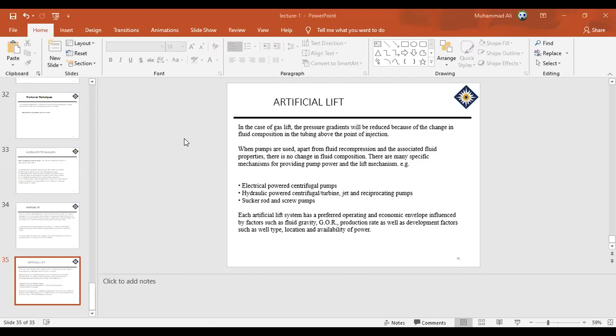Sometimes the well is damaged, formation damage. If you remember the first workshop, it was about formation damage. And if formation damage happens, we do this kind of fracturing. But it doesn't matter if it is shale, carbonate, sandstone or limestone. We can do it, as long as there's a formation damage, and we always have to do it for each well. Every well goes through this process of fracking. But in shale, it's more, like 50 times, 100 times. Shale depends on this, but the others, for example, wells in Iraq, do not depend on stimulation like fracking. But you still have to routinely do that.